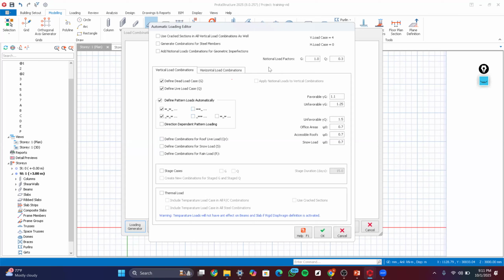In the advanced class, we're going to spend the time to explain all these things, why we use them, and how we would actually use them. But basically, it's a technique used by different design codes to estimate the performance of the building under the worst loading condition. It combines notional loadings, dead loads, live loads, and wind loads, and then checks the maximum or worst condition that can lead to failure, and checks the performance of the structure under those loadings, in order to prevent failure or collapse. In our advanced class, we are going to explain that.